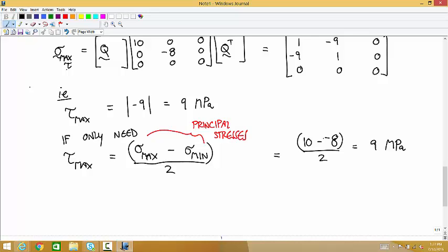And so those shear stresses, whenever you get confused about what a stress means, think of the stress element. So those shear stresses are telling you how much traction there is on the face of the stress element going parallel to the face, whereas the normal stresses are perpendicular to the face. So yeah, I think it's really useful to just always think in terms of stress elements. And really, I probably should have. I'll draw out the stress element when we do this by hand.